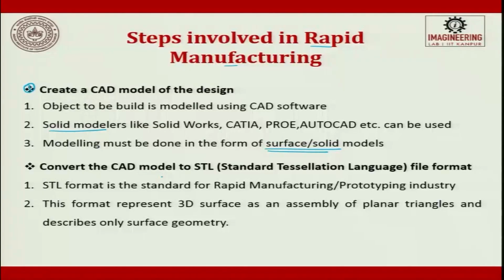The next step is going to be converting the CAD model into STL files. STL is nothing but standard tessellation language file format. STL format is the standard for the rapid manufacturing or prototyping industry. This format represents a 3D surface as an assembly of planar triangles and describes only surface geometry. So, we have a solid, and now we are talking about only the surface.